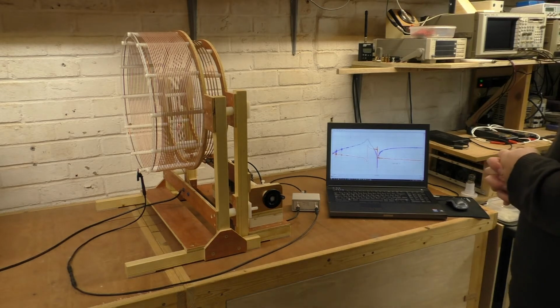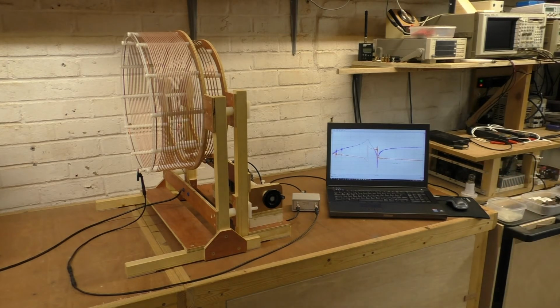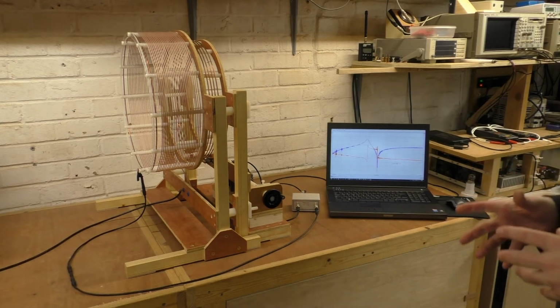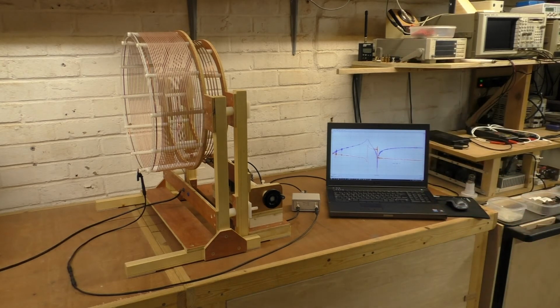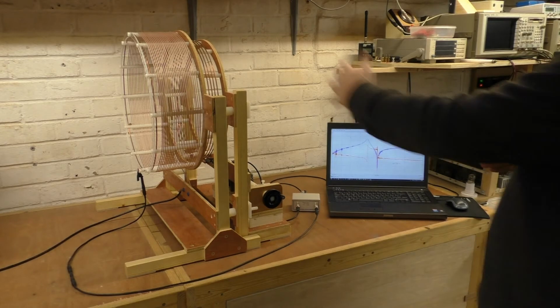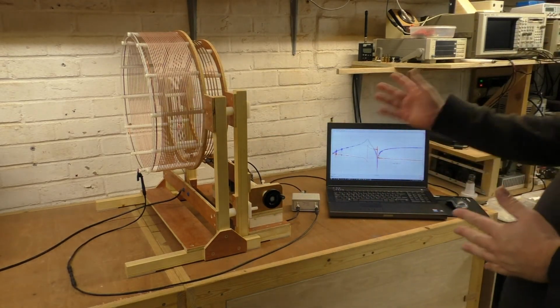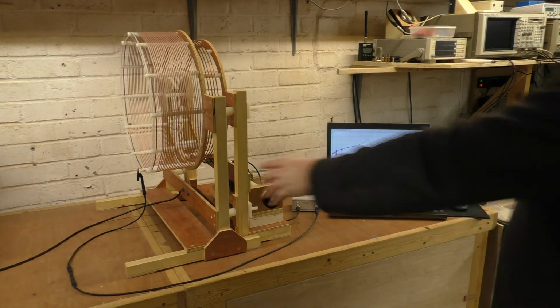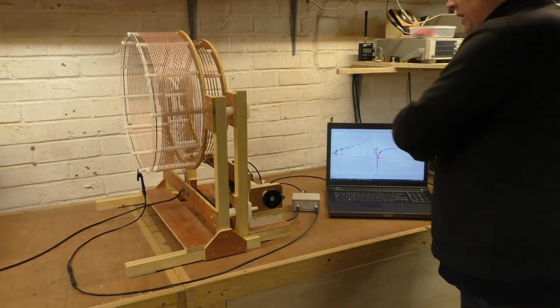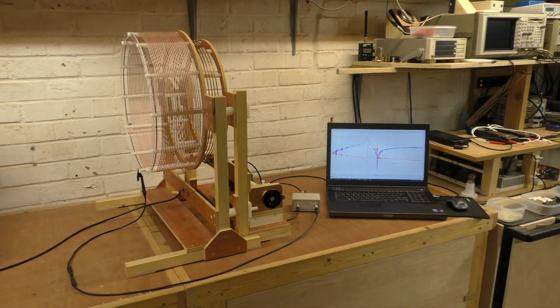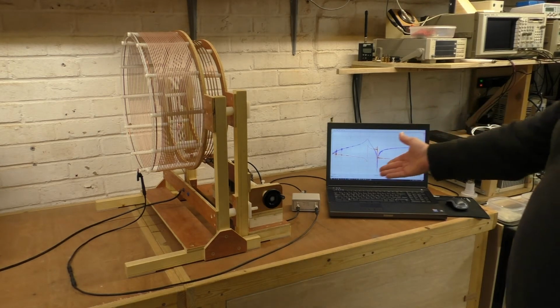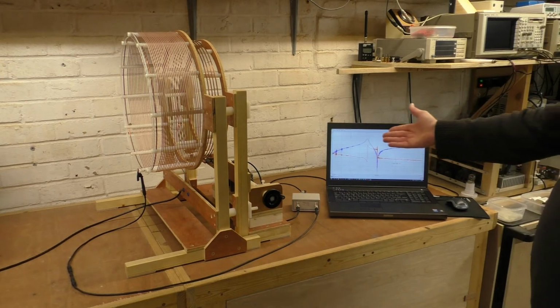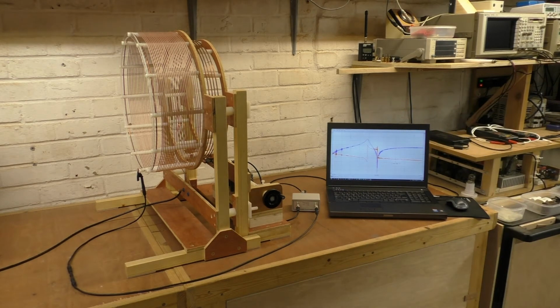Now, as I said before, the Tesla coil in this measurement is a passive component. In other words, we don't have a power supply attached to it, feeding it power. Therefore, we would not expect to see an overall power gain from the input to the output. It is a passive device, so the amount of power coming out we expect to be less than the amount going in. If there were just a wire connected between the two, we would read a straight line at 0 decibels.